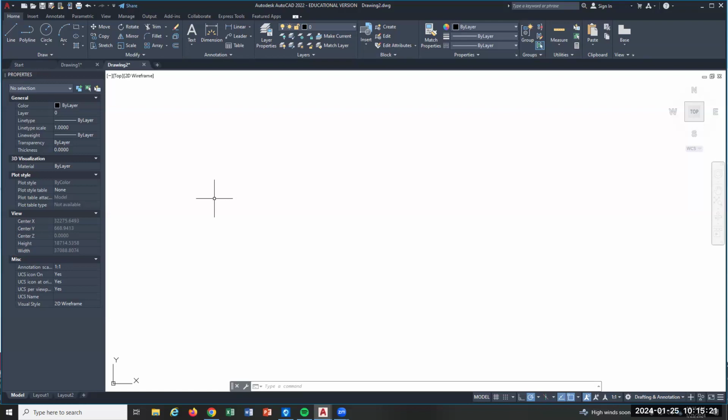So there's hotkeys, like line is L and enter. Now I'm drawing a line, and I didn't have to go up here and click on that. Most of you will be palette button drivers because other software is driven that way. But I am definitely a typer. So most of the time when I'm driving, I will be typing. For instance, Z enter is zoom. So if you don't want to use the roller mouse or it's not working, because the roller mouse has a limited zooming capability.